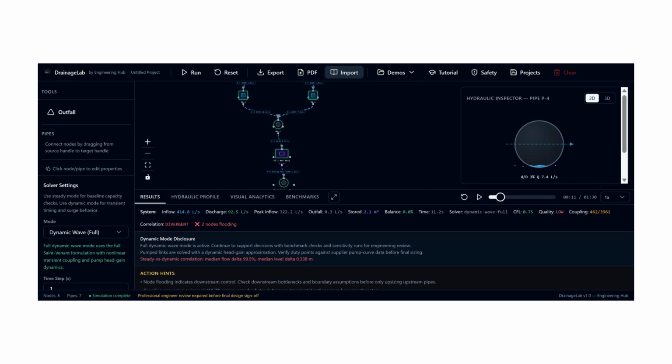Now, this solver is executing an implicit Newton-Raphson junction solver to find the exact quadratic intersection of the pump's head loss curve and the system's dynamic head on every time step. With this, we are able to see the flow climb and stabilize as the head changes. And we are also modeling localized minor losses. This is done by defining junction loss coefficients.